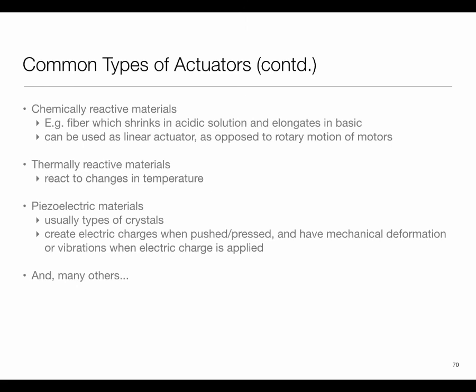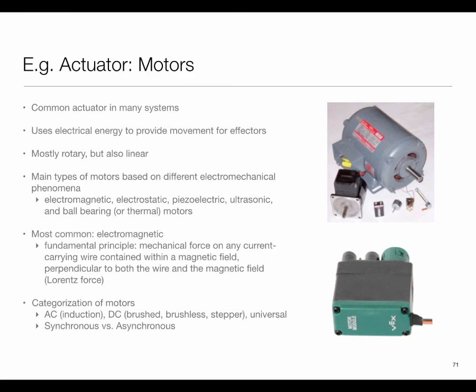So making appropriate use of these hardware capabilities becomes quite important when you are generating signals. And likewise, when you are sampling, for example if you have to sample a signal every 1 millisecond, then counting milliseconds within your program versus setting a timer to generate a 1 millisecond interrupt and then doing things on it, the latter would be a lot better.